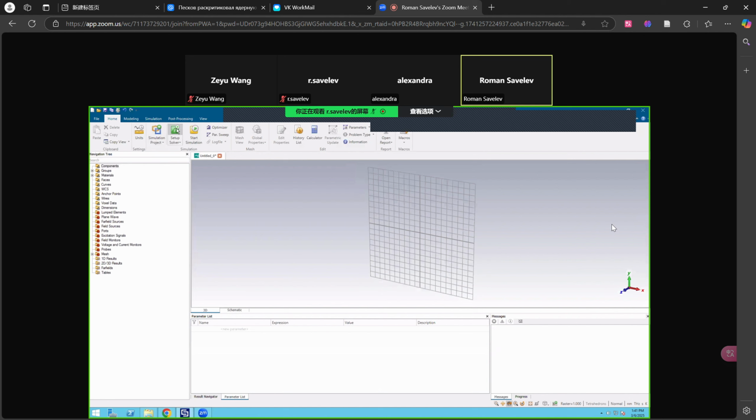You use the frequency domain solver, for instance, and there is an option to find eigenmodes of the port only. We can also use the time domain solver and find the eigenmodes of this waveguide port.